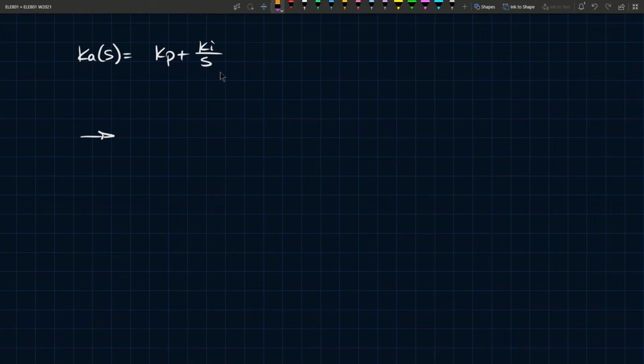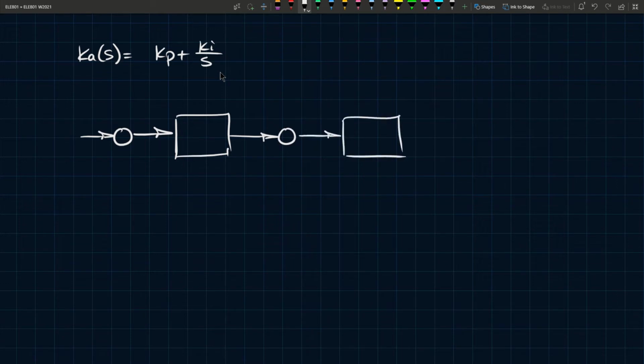Before we do that, we should probably go to our feedback. So your control should look something like this. This will go into the plant, and the plant is modeled as follows. So this is 1 over S La plus Ra. And this is your disturbance. Let's just call it E for now, because we've seen above how to generate it. So we don't need to keep drawing that over and over again. And this here will be Kp S plus Ki all over S.